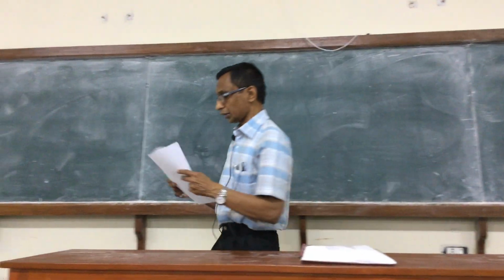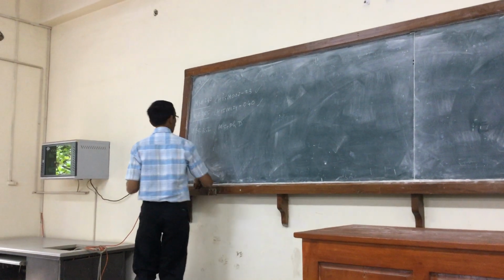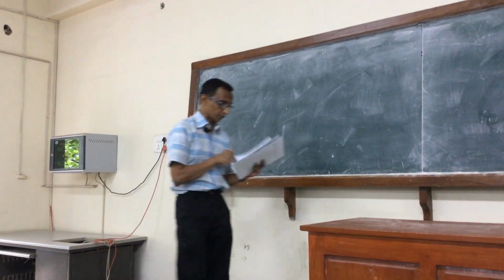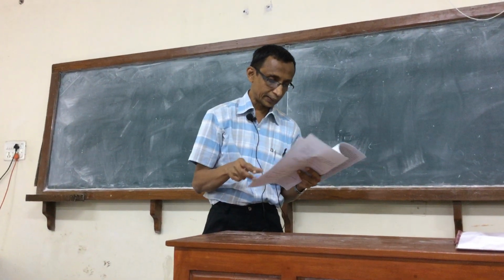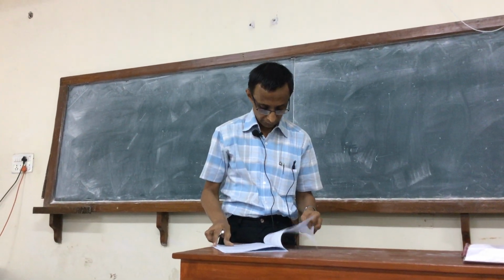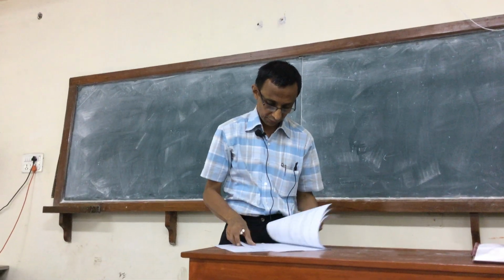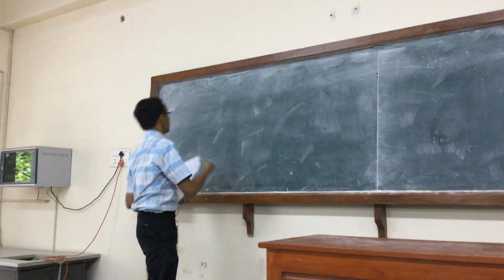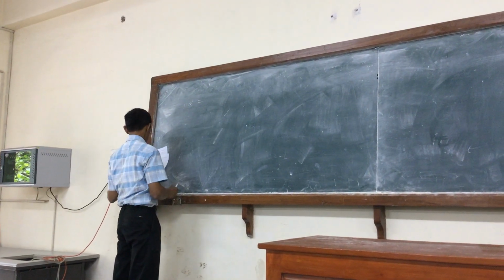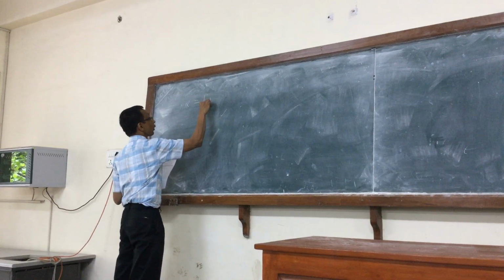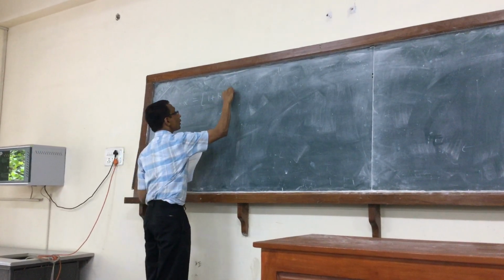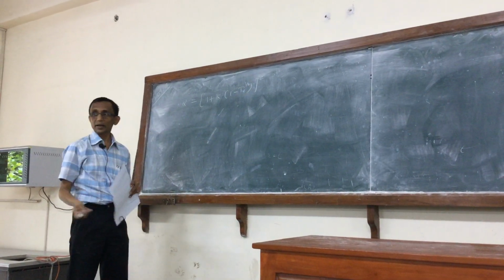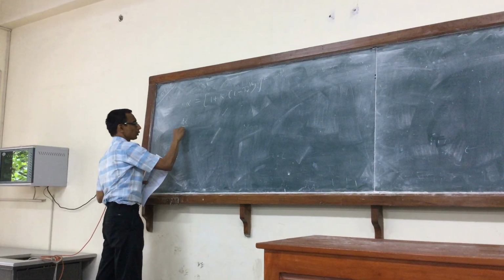So if not, then we continue with what we were covering. One point I forgot to mention was this d alpha by dt that comes in the formula. We didn't quite evaluate it. So for alpha, I can write it generally, illustrative of the equation of state, as alpha equal to 1 plus kappa times 1 minus root Tr, the whole square. So when I calculate d alpha by dt, the formulas are all there in the book.